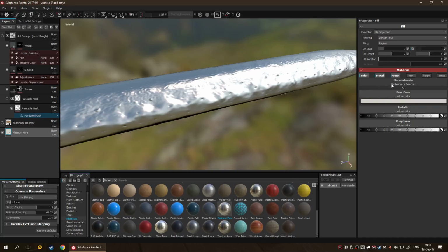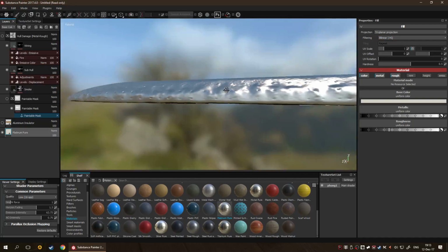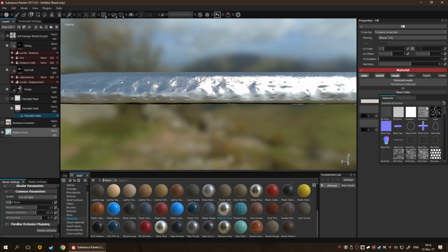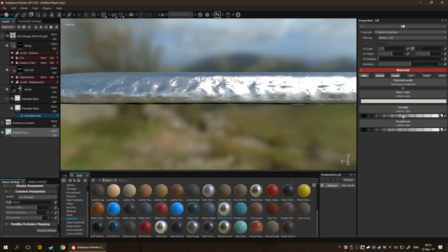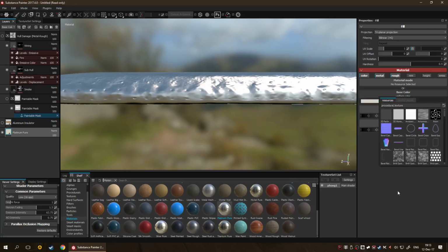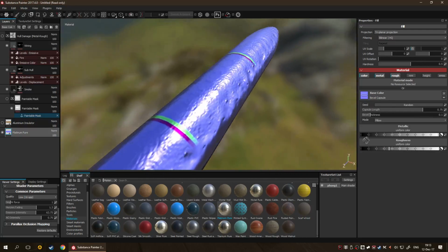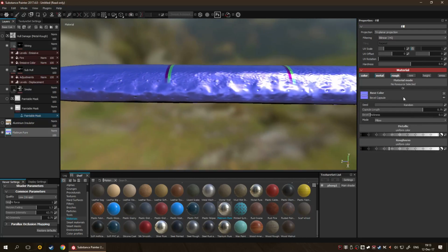Now, again, you can use a particular material, and you could use a different projection. So let's say we're going to try triplanar, and there's really no difference since our UV is bad. But I'm going to show you a little trick where you might be able to fix some issues. Again, you can select a particular material here in the base color. So you could, sorry, not material, but a mesh. So let's say you want to use this. This is your base color from now on, and this is your texture essentially. And again, you can play with all these settings here, such as capsule length, etc.